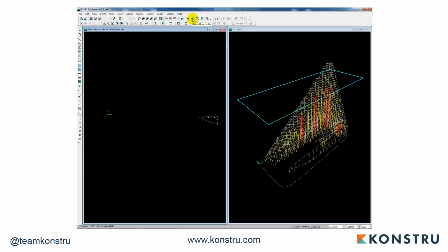Now, the downside with this kind of workflow is, this is great for very early design, if the building changes so drastically that you essentially need a new ETABS file every single time anyway. But once you're later on in the design phase, once you enter DD or CD stages, this is not sustainable anymore. We don't want to basically have to regenerate a whole new analysis model, or let's just say a whole new documentation model every single time.